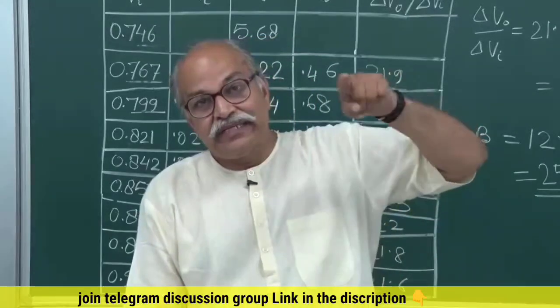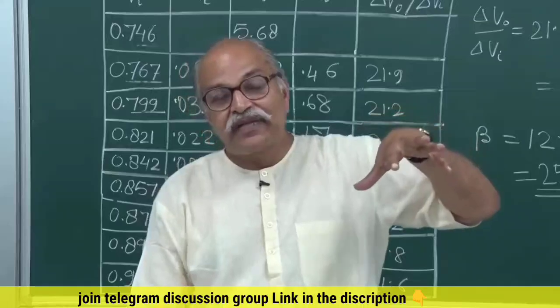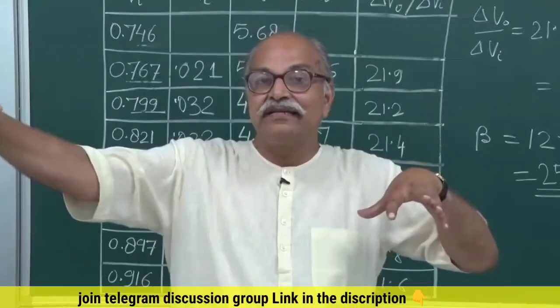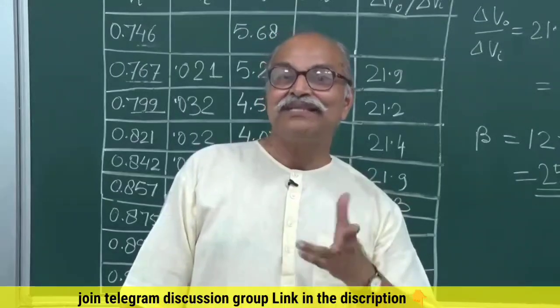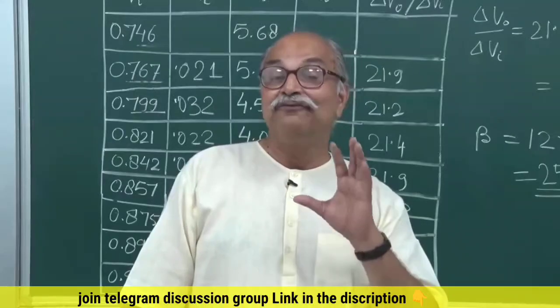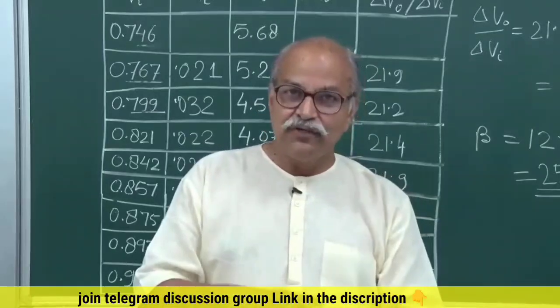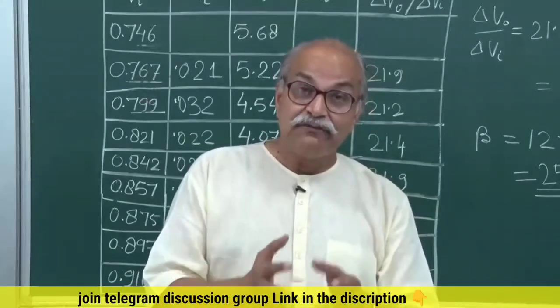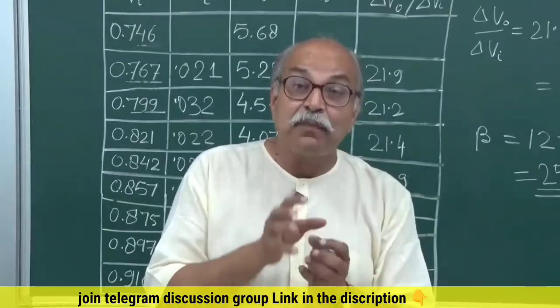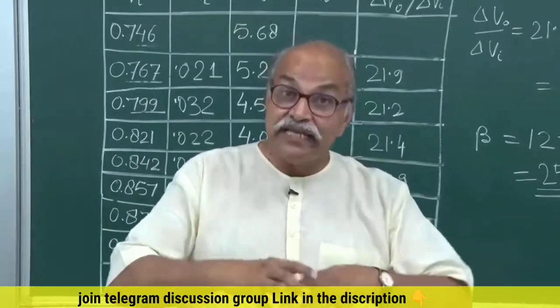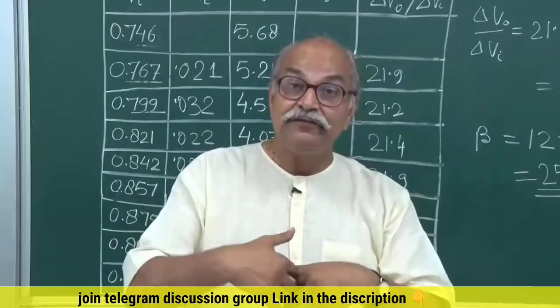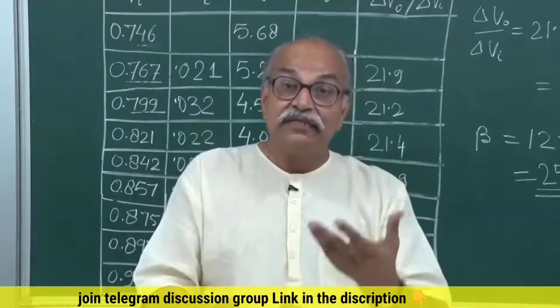So what you are doing is you are controlling a large current circuit through a small current circuit. You are actually doing switching in that base circuit, that VBB, that forward bias of the base emitter junction. You are somehow changing that voltage from a low value to a high value. The voltage that you apply to that base circuit, you change it from a high value to a low value, from a low value to a high value. That is the switching.